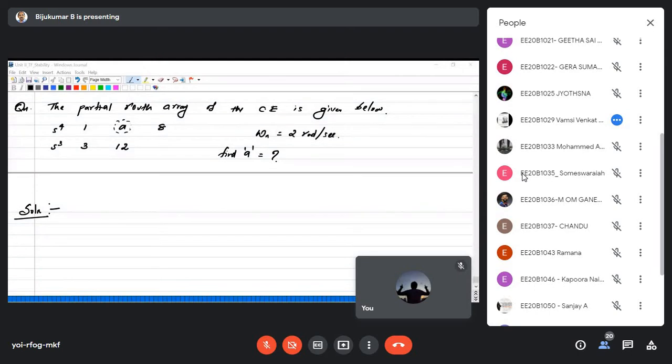If I want to place the pole on the S plane, where will it be? Yes, sir. According to your calculation, since given a fourth order characteristic equation, taking A equals 6, we get the fourth row as all zeros, sir. So there must be an oscillation in the system. So there must be two poles lying on the imaginary axis, sir.